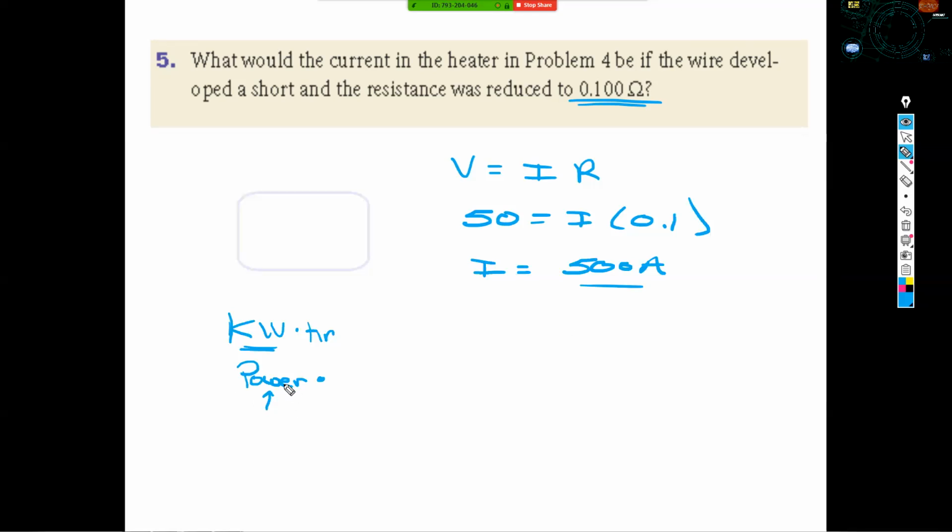A lot of times, when you buy a microwave, they're typically about 1200 watts, or you look at a 60-watt light bulb. But again, you have to use kilowatts, multiply by the time, say your light bulb is on per day, per month, and then multiply it by the rate that the electric company charges you. And again, I'm going to have a worksheet with some tutorials and a couple practice problems for you to figure that out.